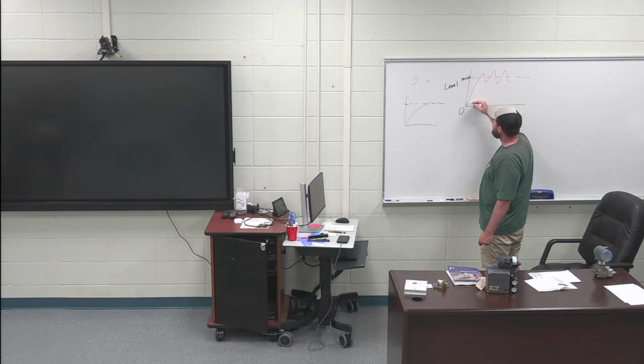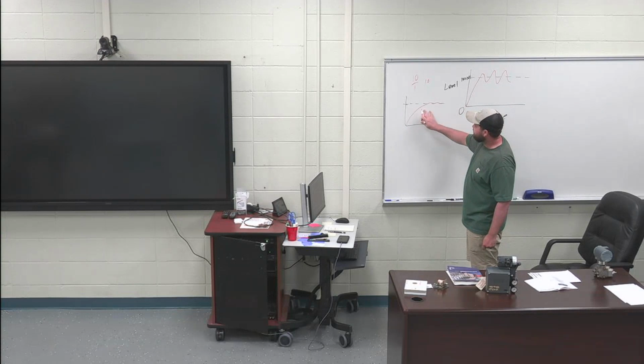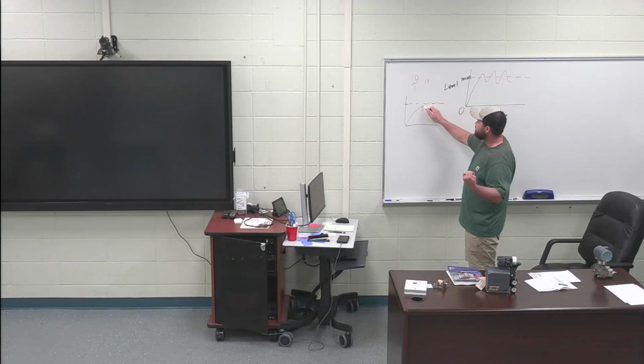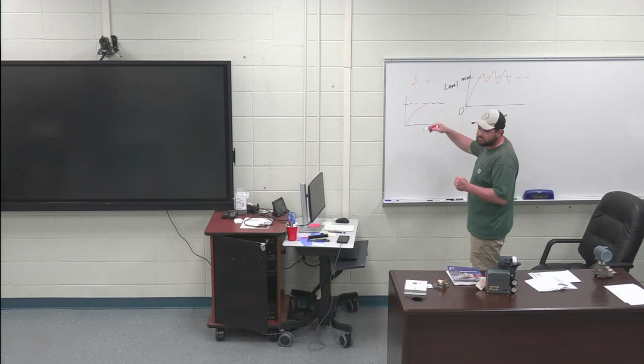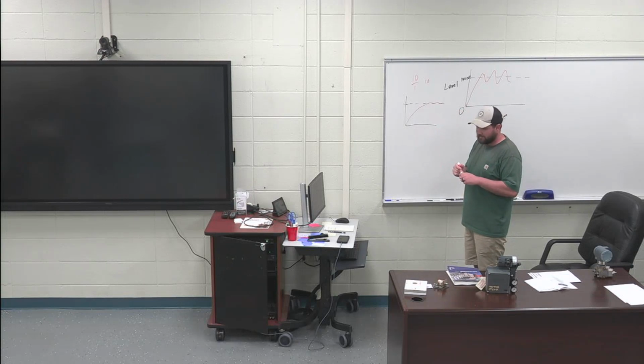The goal is to have your gain turned down enough to where you can just keep going, say open, open, open. We're getting close, so close that valve down a little bit, bring that output down a little bit, and then you can get that sweet spot of 55% open, which is gonna take care of what our signal needs to be. Does that make sense?